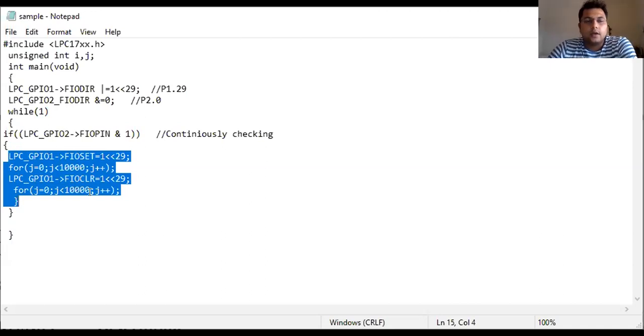So in this regard, we are continuously using the system resources. And when you are using the system resources, it is not an efficient way because we don't know when the user will provide that input. The user can provide that input without delay, or the user can take as much delay as possible. So we don't know how much delay is going to be prior to you go inside the loop. And prior to that, still your processor is continuously on. So in that situation, if you want to tackle it, we know the interrupts come into play.